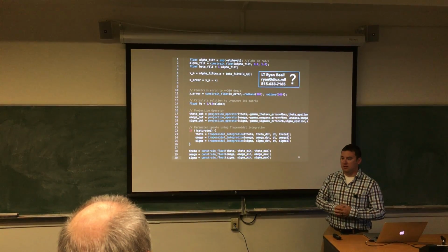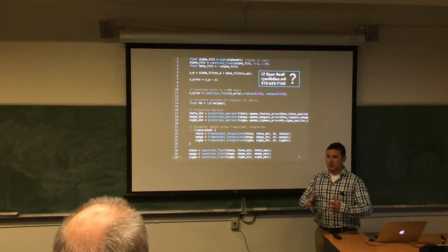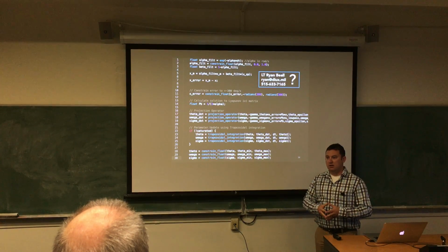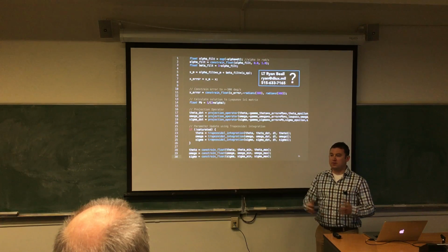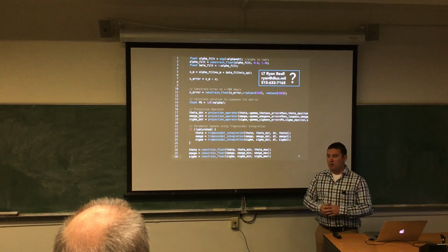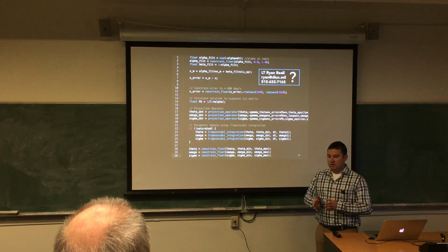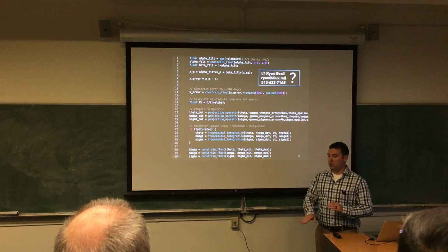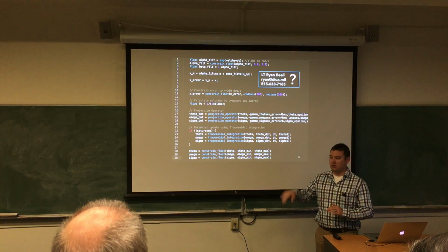One thing I noticed right away was that when you tune a PID controller, it's sort of arbitrary and you just have to take an initial guess. If you get that initial guess wrong, the controller can just blow up. The plane will go completely unstable and almost like destroy itself. With this architecture, I never saw that. What you saw was a laggy control that was obviously underperforming. The control was just hunting. It was just way behind the aircraft, and it would just oscillate really slow.